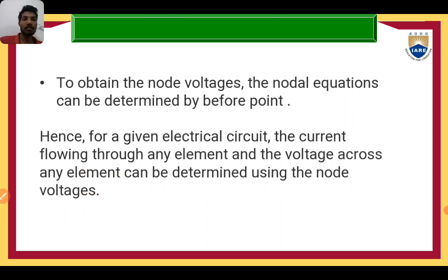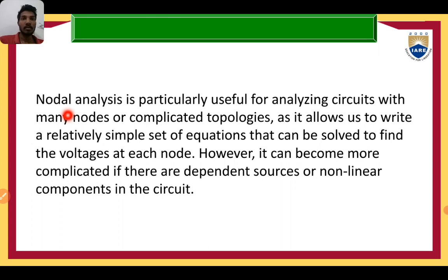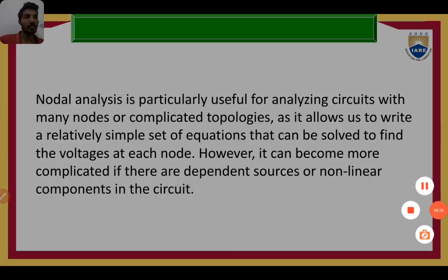Nodal analysis is particularly useful for analyzing circuits with many nodes or complicated topologies, as it allows us to write a relatively simple set of equations that can be solved to find the voltages at each node. However, it can become more complicated if there are dependent sources or non-linear components in the circuit.